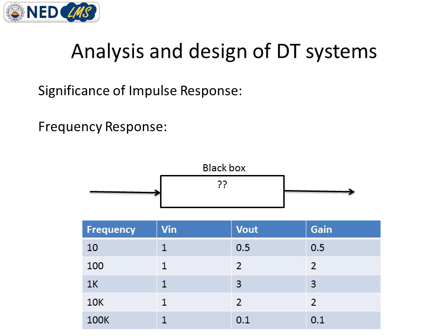So in this way, impulse response tells us the characteristics of the system, because impulse response is the output for an impulse. It tells us the behavior or natural response of the system, because whatever output we get after time n is equal to 0 is purely because of the system characteristic, since input is only applied at n is equal to 0.